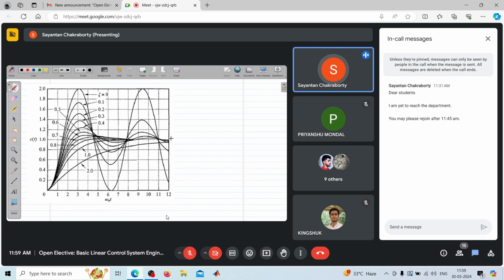So, see, this response that it's exhibiting with respect to its position is not due to the external force, but due to initial condition. That is, initial condition means it has a height or a position. That is the initial condition, and based on that, it is giving you a response. The more you lift it above the table, the more potential energy it will gain, the more initial value of energy it will contain, and the response will take much longer time to settle down.